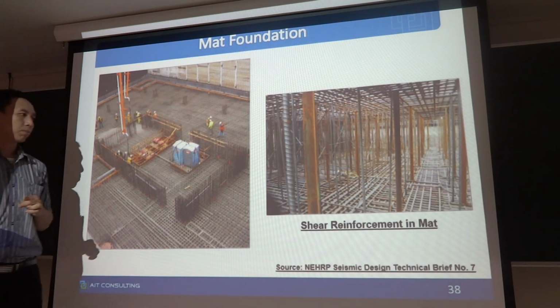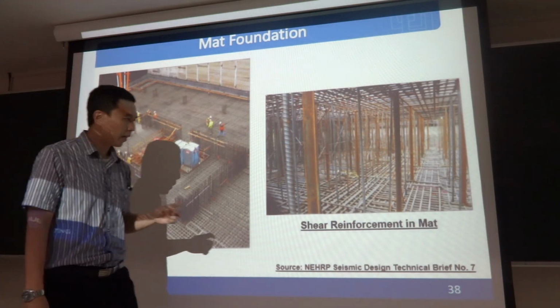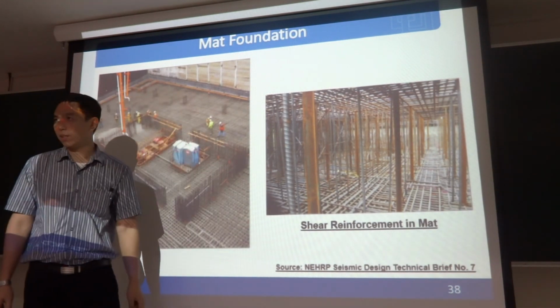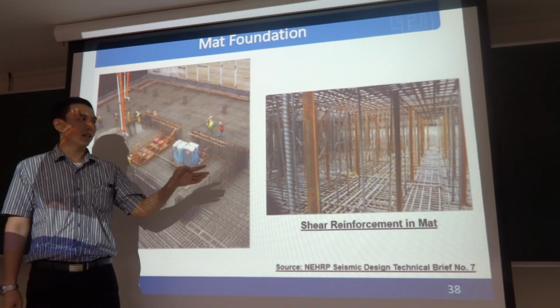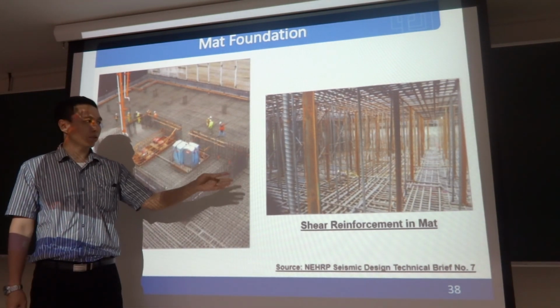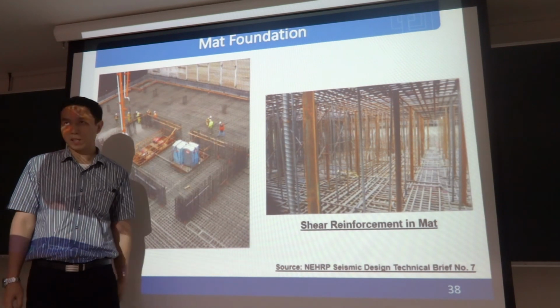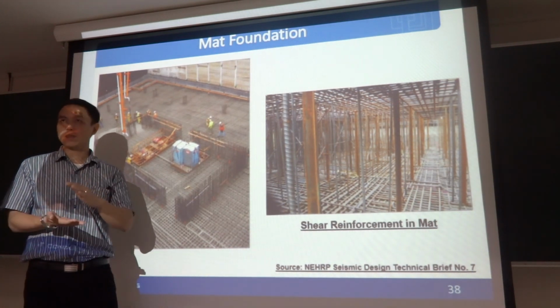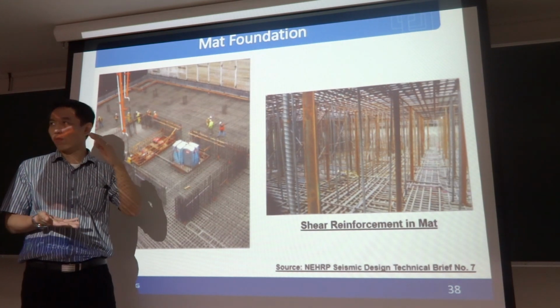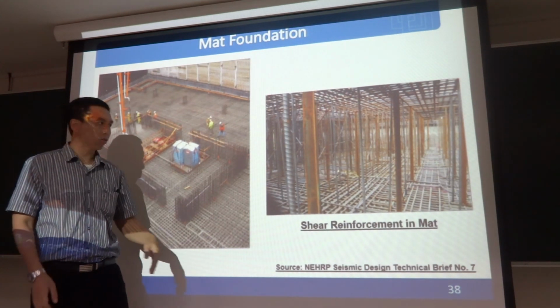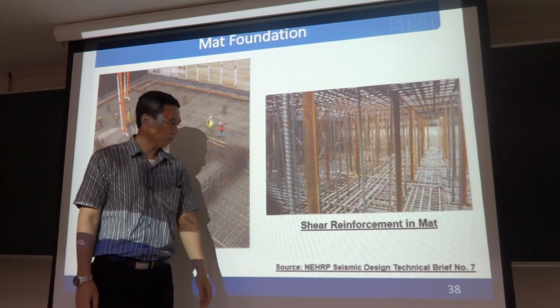Normally we do not provide shear reinforcement in the mat foundation. We try to design so that the shear demand is resisted by the concrete alone. But sometimes, if there is a limitation on the thickness of the mat, we need to add shear reinforcement.